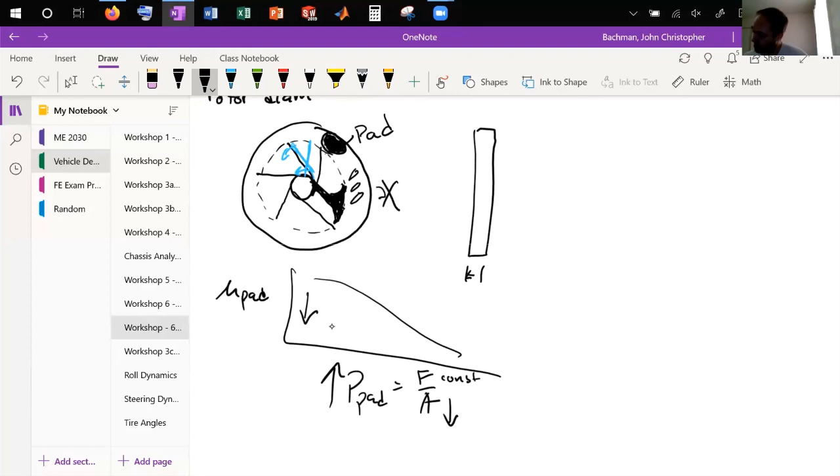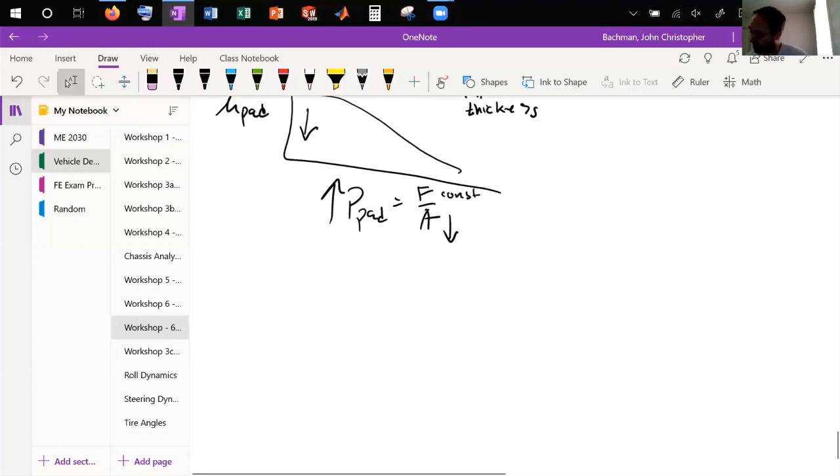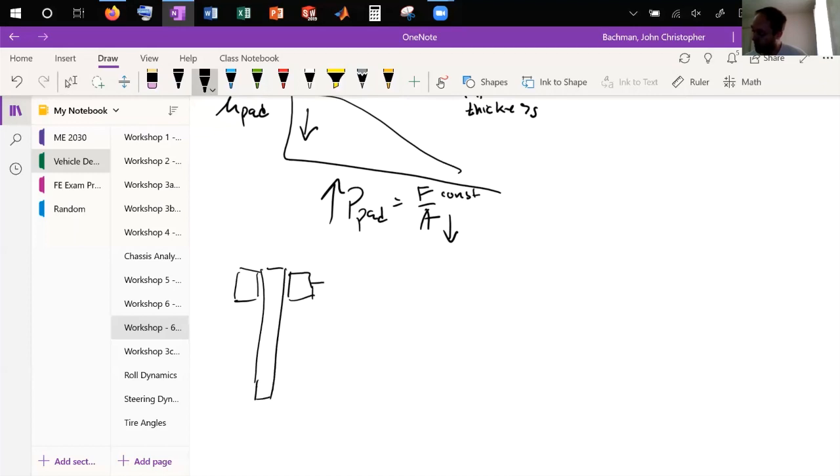I was trying to design the thickness, right? Just the thickness and the spokes. And some other things to think about is that the pads, when they come on to your rotor, the only thing that moves them back off typically is the play in the rotor. So there can be a lot of friction associated with that.